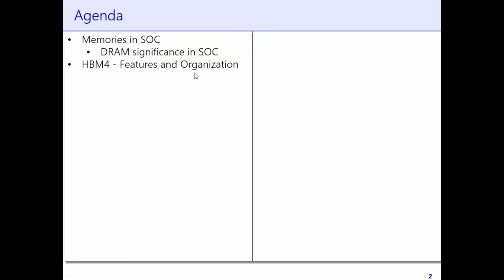As we go forward, we'll see that HBM4 is built onto the SoC through something called the interposer and through silicon vias. That allows us to keep the HBM4 memory onto the chip. Generally, the DDR is placed around the SoC on the motherboard, which increases the trace length of the connections between the processor and the memory. Whereas in HBM4, since the memory is kept onto the SoC, the connection length will be very small. It will be in millimeters, but it brings its own challenges.